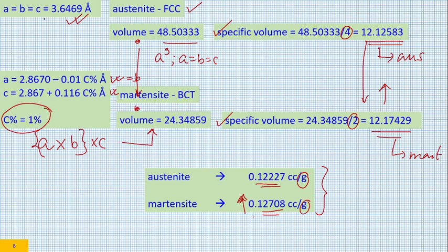So if I tell you that there is a kind of transformation happening because of grinding or any other manufacturing process, and you know the crystal structure and the unit cell, by looking at the metallurgical transformation, you should be in a position to predict what kind of stress it would incorporate. Would it incorporate compressive stress, or would it incorporate tensile stress? So 2 aspects are covered.